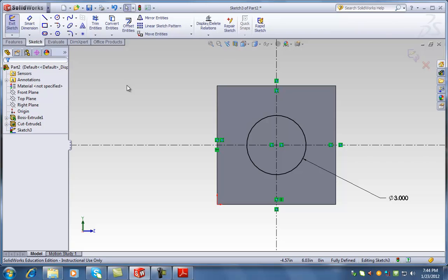Well, you're not in sketch mode. You need to click on line. You need to select the plane normal to and then click on line. I'm in normal 2 and I'm on lines. Is the sketch mode? You see this on the side? Yeah.